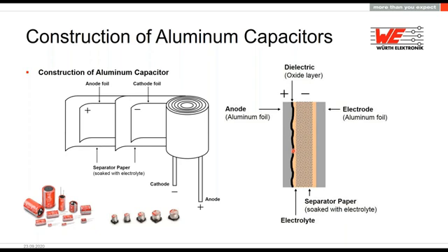We also use the electrolyte and the foil to contact this electrolyte to the outer world. So not really the cathode foil is the minus; it's more or less the electrolyte and the oxide layer. This is quite special. But of course we have the two pins to connect it to the PCB.